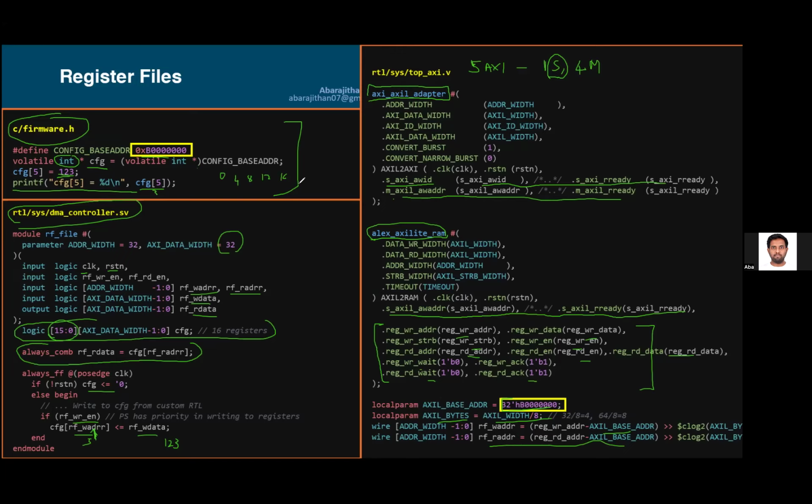It will give addresses like that. You take those addresses and put them over here, and now you're going to have a problem, because this is the first register and this is the second register. So you want to change it into 0, 1, 2, 3, 4 to be read in Verilog, right? Because in C it's in bytes, in Verilog it's in words. That's how we have designed it.